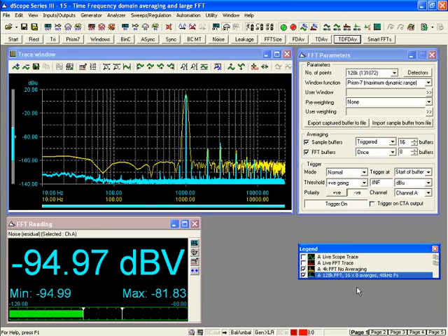Well, in this case, the blue measurement, the very high resolution FFT with lots of averaging and a low sample rate, we can now see very, very low level intermodulation, noise and distortion artifacts that we weren't able to see in our original measurement. So it just shows you how you can enhance your ability to see these products. And in fact, I should clarify that the noise has been partially averaged out. So this is really for looking at the correlated distortion and crosstalk products.